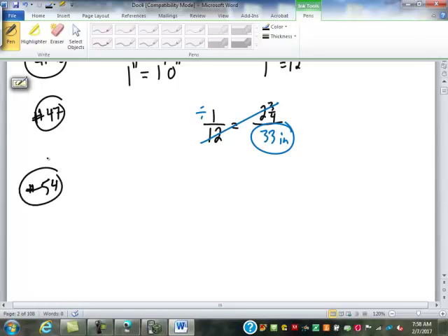We've done these gear problems and we actually had the number of teeth. We can still do it with the gear ratios. So our gear ratio A to B is a 5 to 1 gear ratio. If gear A is turning at 1200 RPMs, how fast is gear B turning? Well, A is bigger. Does B have to be turning faster or slower? Faster. Smaller gears got to go faster.